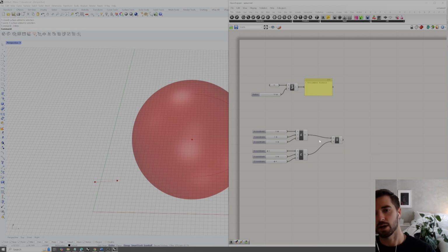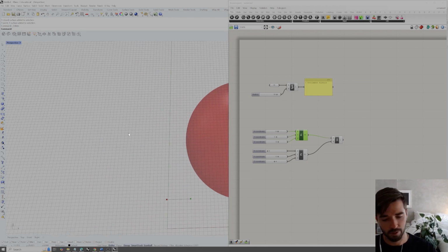If we didn't want to constantly be copying one component and all of its setup to the next, which is an incredibly inefficient way of doing this, a different way is to use operators or operations, kind of like we did in Rhino. So one way is in Rhino, we could just click to add 2 points. So if I go into our Rhino interface, I can type point, right? And I can click 1 point. I can perform that operation again, click another, type line, and I can draw between those 2 points.